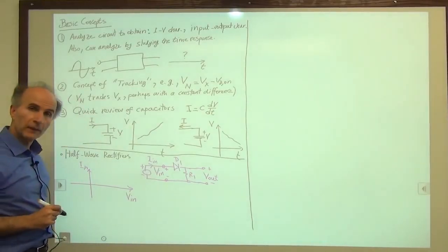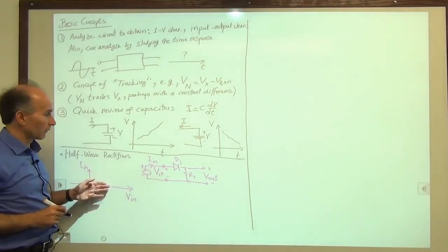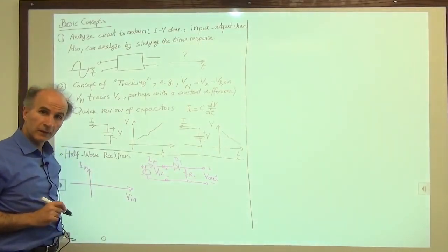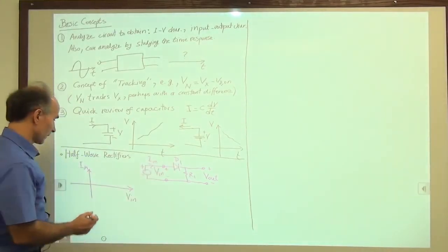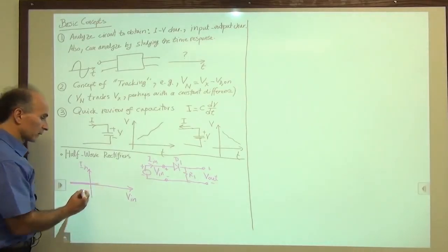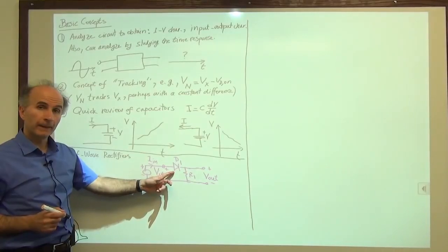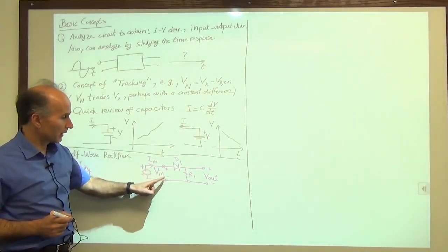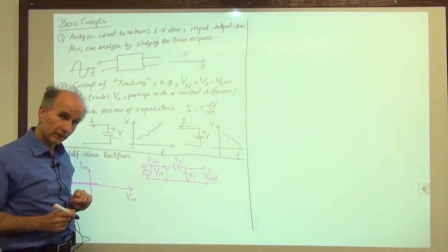All right, so we start with V in at minus infinity and come forward. If the voltage is very negative from here to here, this diode is off. So there's no current. There's an open circuit, there's no current. So I in is 0. At what point does the diode turn on? It turns on when this voltage from here to here is equal to VD on.